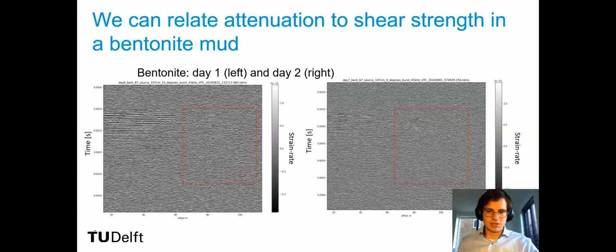further upscale. This concludes my presentation, in which we showed that with using DAS, we can accurately determine the water-mud interface, the most accurate, non-invasive way to do so to the best of our knowledge. In addition to this log setup, we want to add a straight fiber to which we can tie these logs. Monitoring the nautical depth is yet another example of how we researchers and engineers with DAS at our disposal can potentially change current measuring techniques.